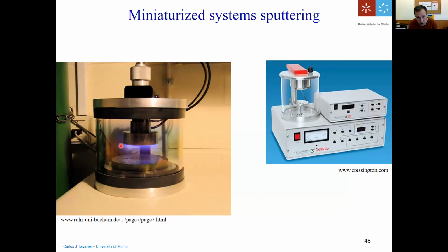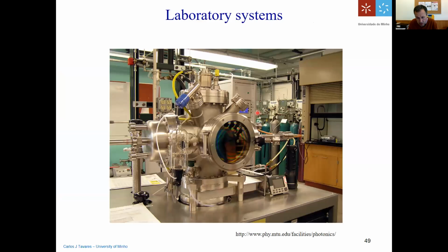And normally you just use a very small sputtering chamber. Here is your magnetron, which has the magnets, and a very thin gold target, about 0.5 millimeter. They are very expensive. Then you place your samples on the bottom and you sputter down, and you make the gold film.